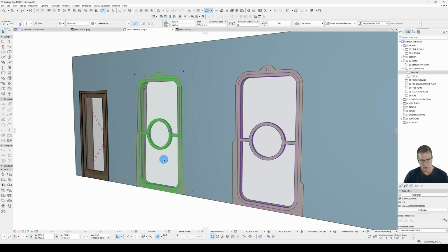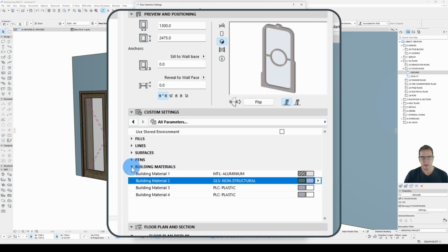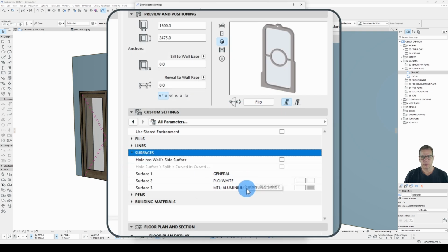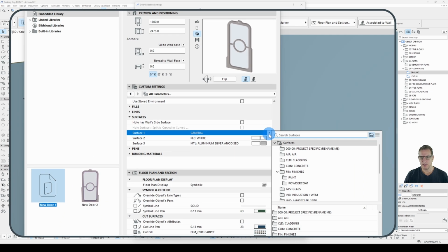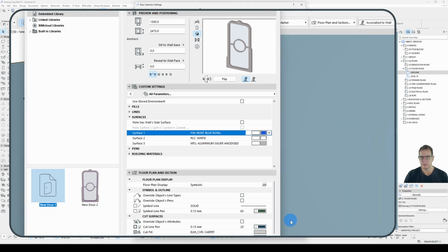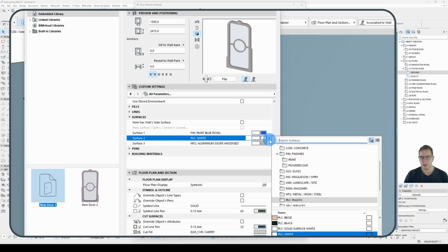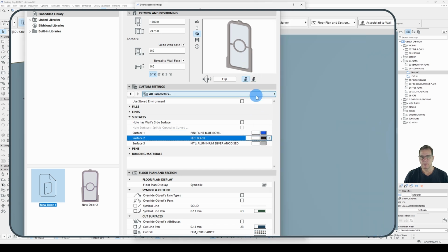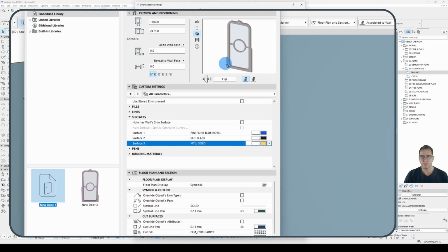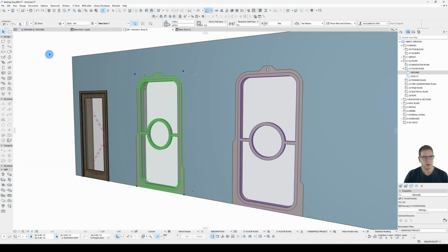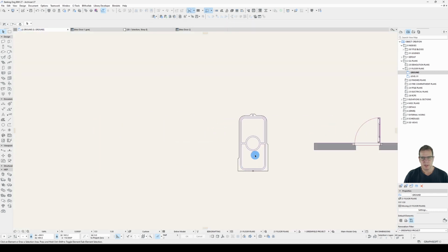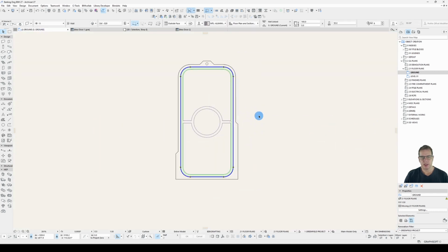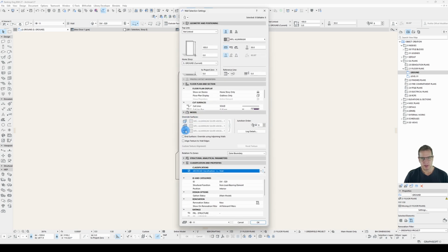And if we have a look at the surface parameters that were created, I've got 3 here, and they don't have any impact at all. So if I change these, they don't have any impact on the final outcome. And why is that? The reason is that a surface parameter should only be created if your surface is overridden in your base geometry.